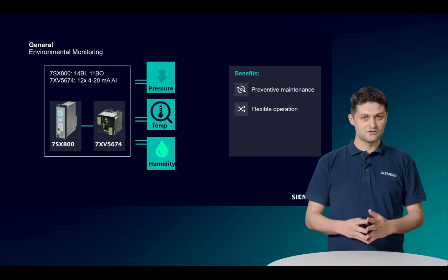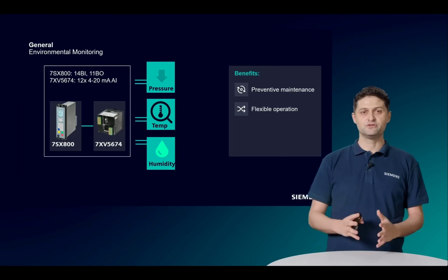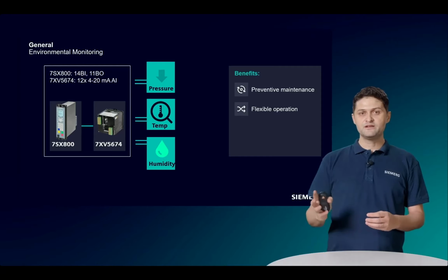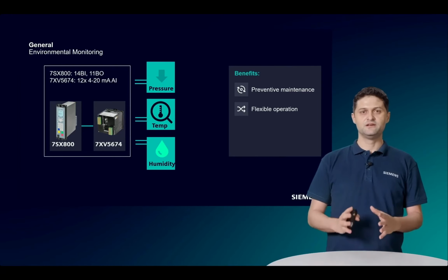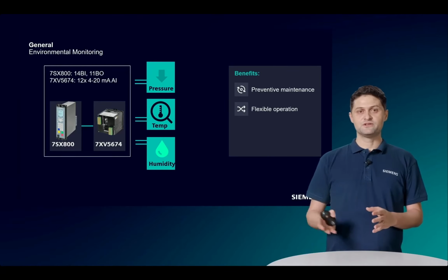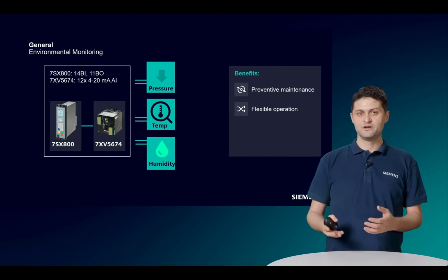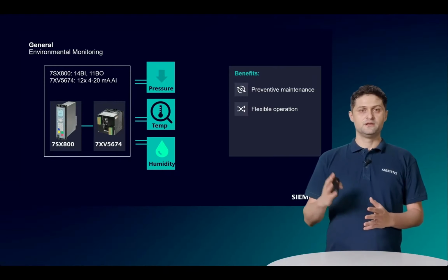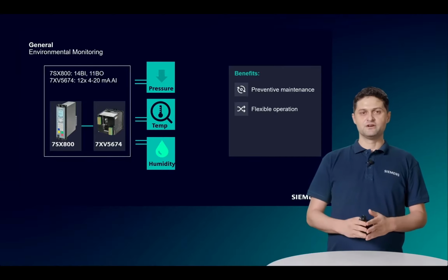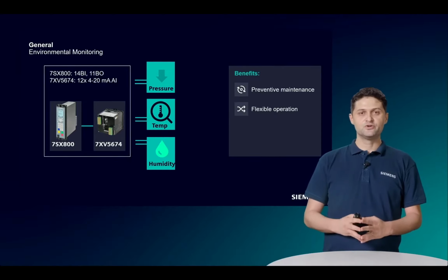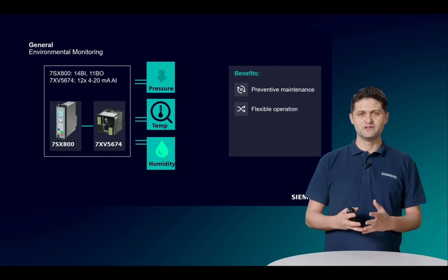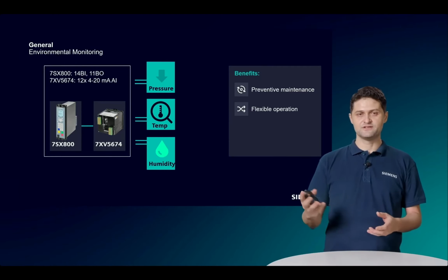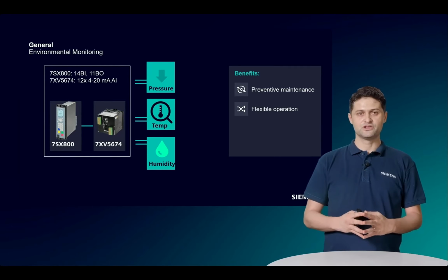In this context, using Modbus in SIPROTEC 5 to monitor cable joint temperature will give predictive maintenance possibilities, which at the end of the day increases reliability, uptime of the grid service, and which might supply to the critical infrastructure like hospitals and reduce the risk of damage to physical equipment. The same monitoring applications can be extended to high voltage GIS systems, where internal monitoring of the overall switchgear gets more critical as the size of the installation increases. SIPROTEC 5 gives a very flexible and scalable solution with Modbus client.